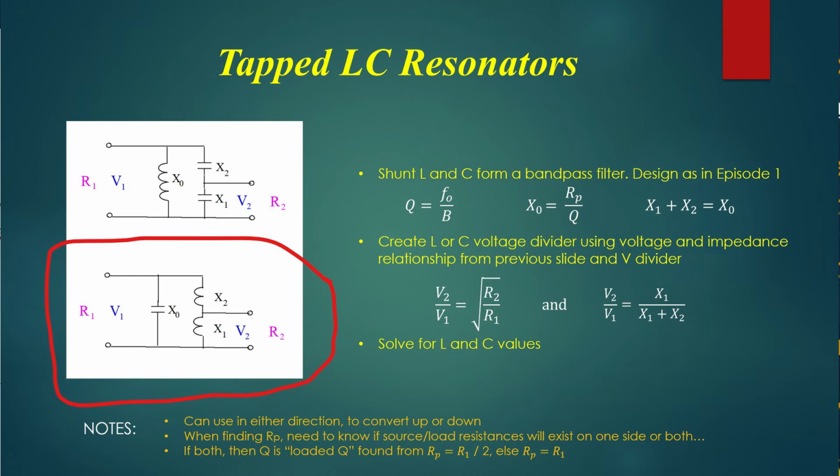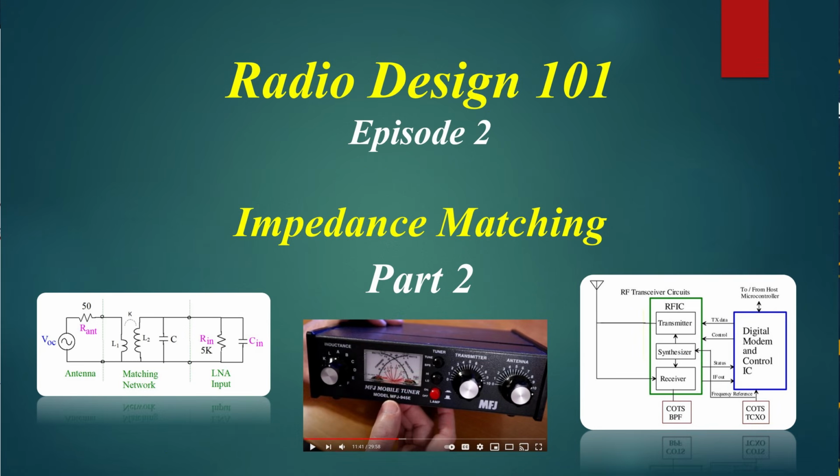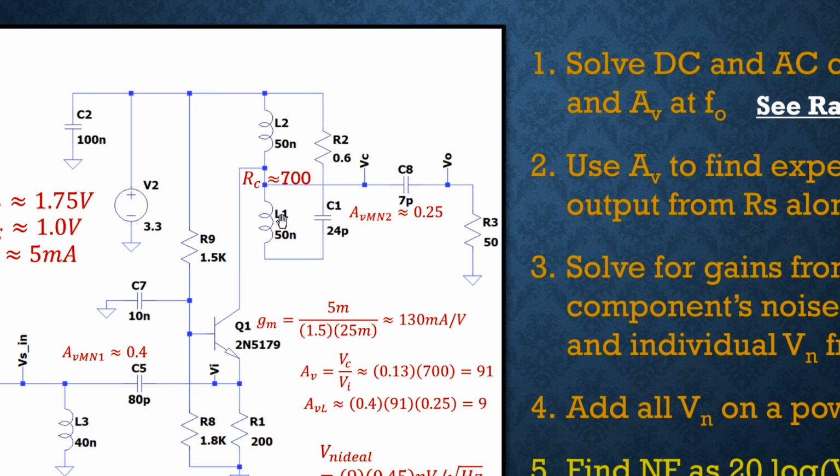This split inductor circuit was covered in one lecture of Radio Design 101, and what happens is, because these two are equal, you get about a quarter of that 6K here, or about 1,500 ohms. So 1,500 ohms to ground from the LC tuned circuit. But oh wait, look, there's a load over here, and there's the matching network. And when I converted the 50 ohms at the load to what it would be looking in here, that was another 1,500-ish ohms.